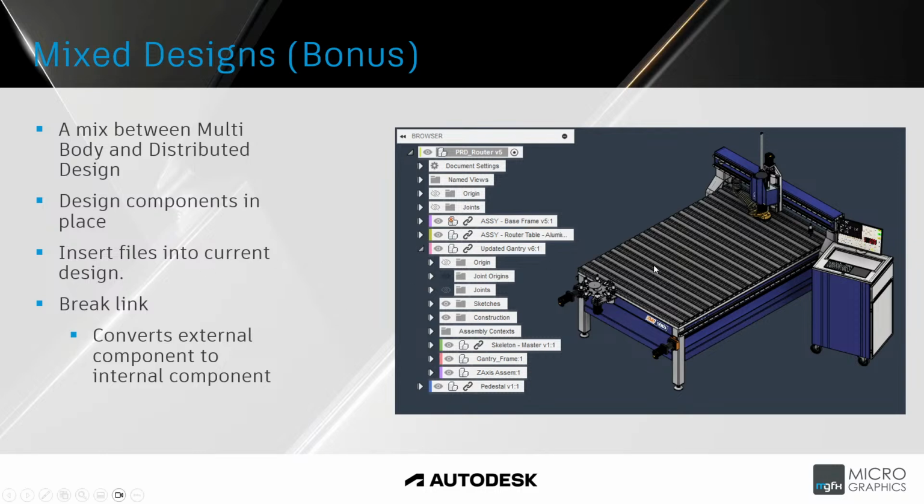This router data set that Autodesk provide shows us a couple of components or sub-assemblies that are linked in. So we can see there's the assembly for the base frame that's linked in, but we also have some components like the gantry frame or the Z-axis assembly that are built internally inside the design. So there's no link, you don't have to have the router assembly open to be able to edit the gantry frame or the Z-axis assembly for this design. So you have the freedom to design components in place or insert files into the current design.